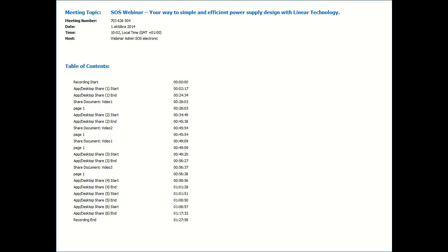So the question was for the part which is plus minus 15 volts, low noise. I can imagine that this is to power some kind of signal conditioning part with probably an op-amp, which requires plus and minus.